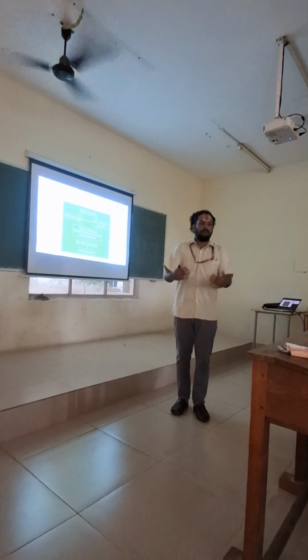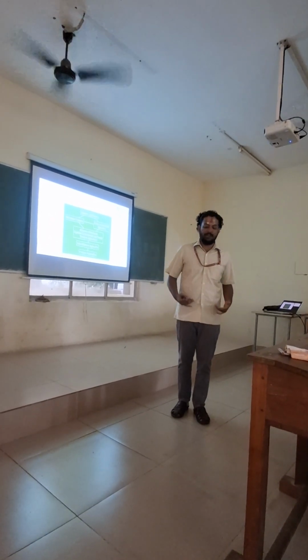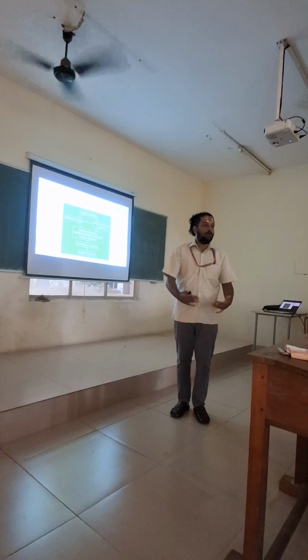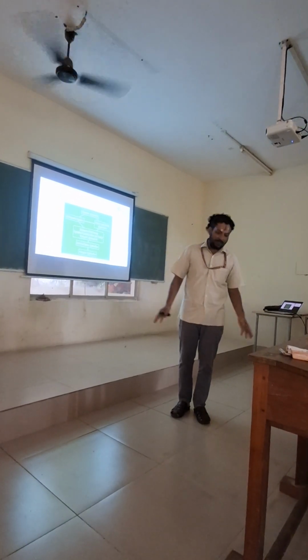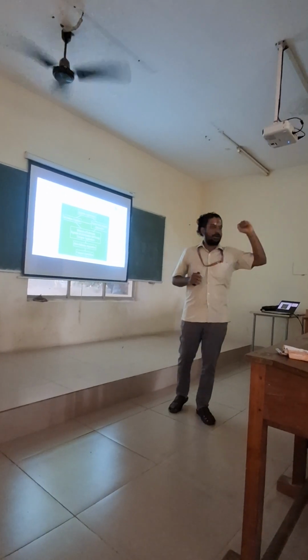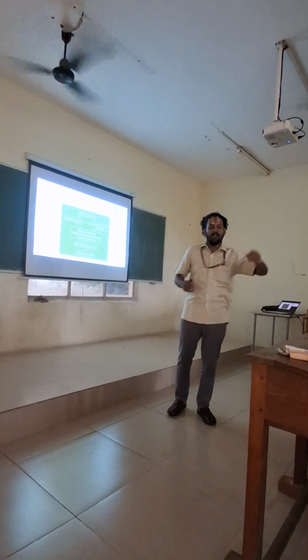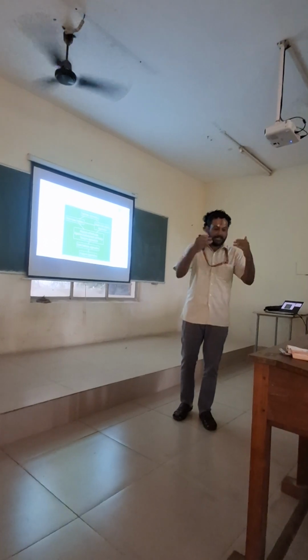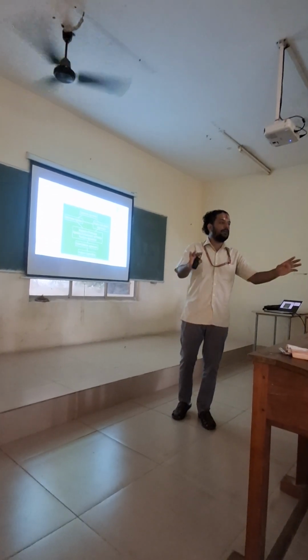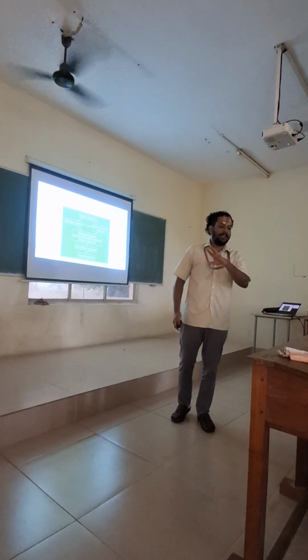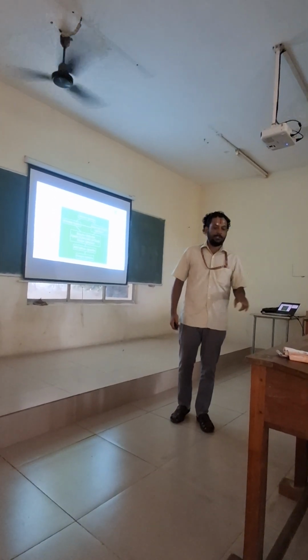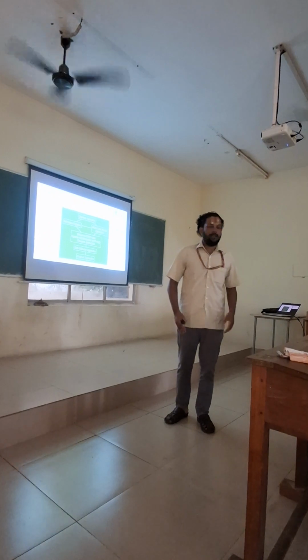This is my free flight time, what I define it as. And then I have what is called a scattering table, which consists of all kinds of scattering events, and I will go fetch a scattering event from the table, and I will say, this is my initial momentum. The scattering event happens, probability of this scattering event happening is this. The code will basically take a decision whether a scattering event happens or not. I will calculate the final momentum.